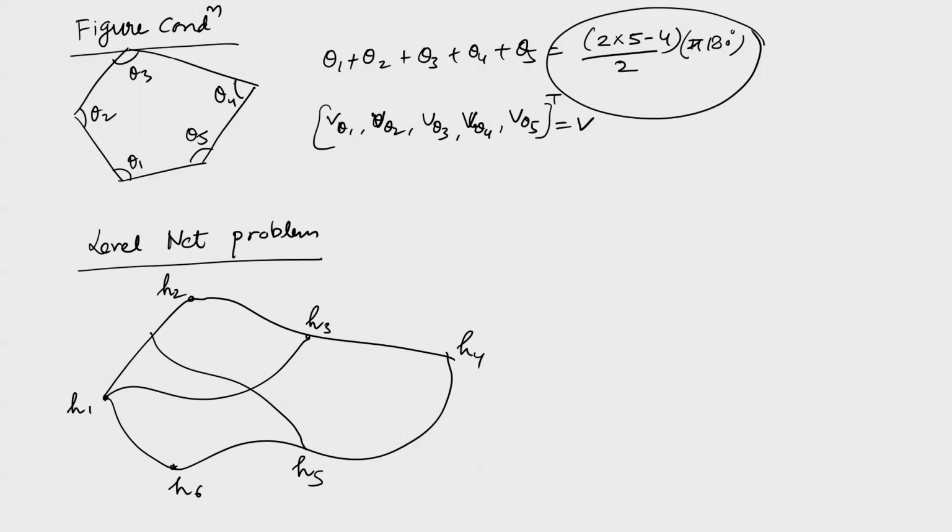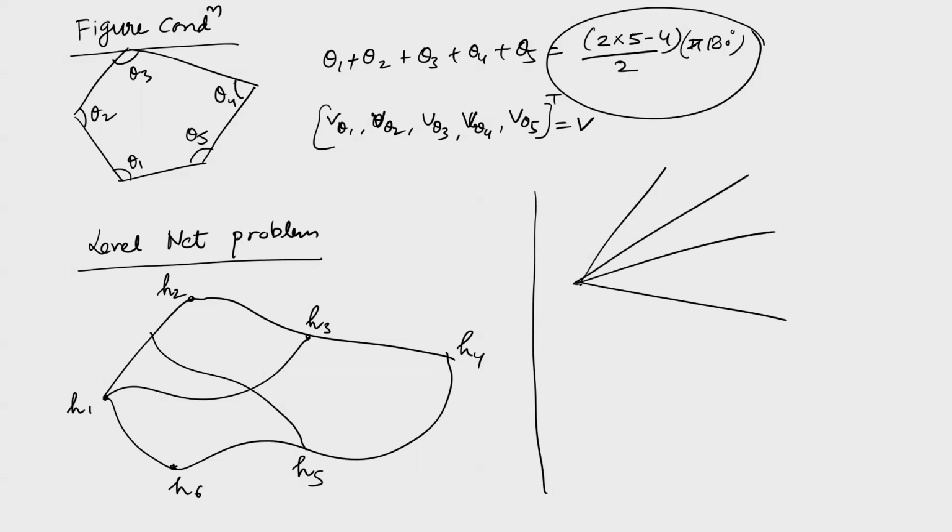You will write multiple conditions. For example, what do you mean by multiple conditions? I will give you another example here, a simple one. Let us say there are some angles like this. First is alpha 1, second is alpha 2, third is alpha 3. Now I measure the combined angle here, alpha 4, and this angle is alpha 5. So I observe all the 5 angles in the field. Now I want to find the adjusted values of these 3 fundamental variables, alpha 1, alpha 2, alpha 3.